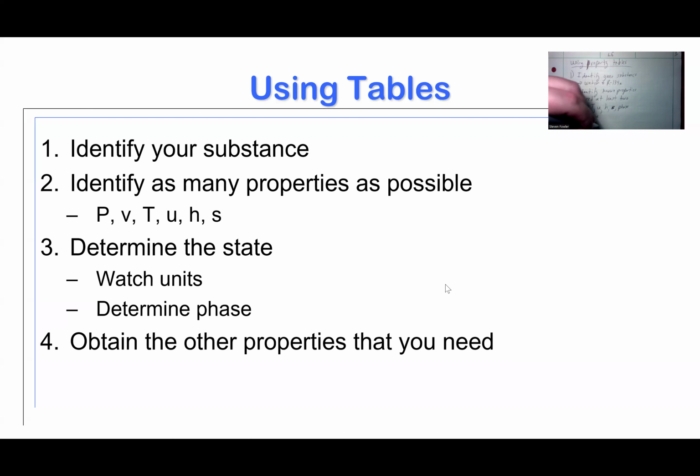Step 3, determine the state. Right? So state is one of those things we said that's in chapter 1. You can read it. It's important. And we normally don't have class time to talk about all the definitions. State is one of those. State means once I know the state, that means I know where I'm at on the PVT surface that we talked about in lecture 5. And once I know that, that means I can describe all of the properties of my substance at that point. So knowing the state is important.